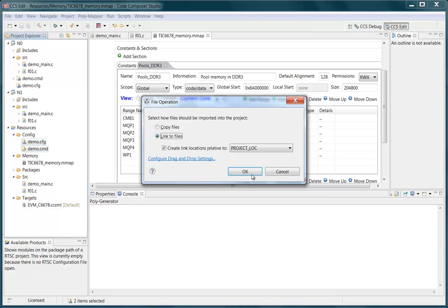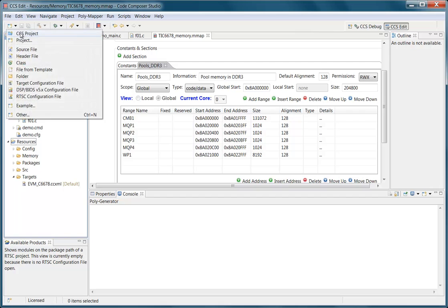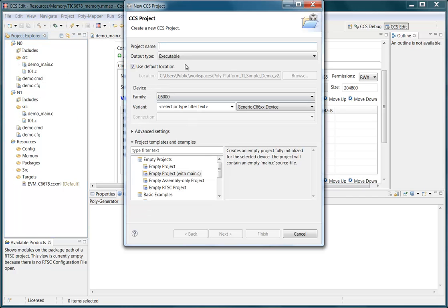The preparations for the demo are complete, and we can work on the multi-core aspects, including defining which parts of the demo will be running on which core. The next step is to create a topology project. A topology project contains topology maps and memory maps, which are used to specify and configure the underlying communications topology. Each topology project can contain many topology maps and one active topology map at any given time.